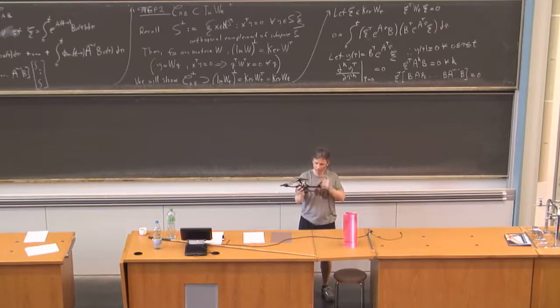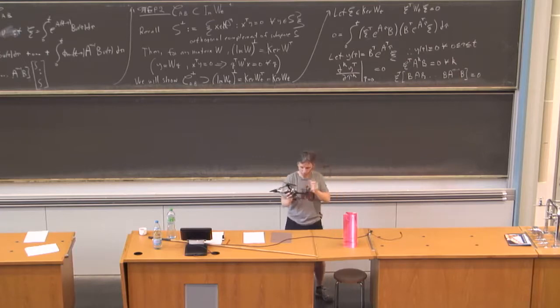But it's often better to think of how these control inputs work together. Think about hover. You want to control this thing about hover. If they all produce the same amount of thrust, you have some equilibrium state. If you want to accelerate up, all of them increase their thrust. If you want to go down, they lower their thrust.